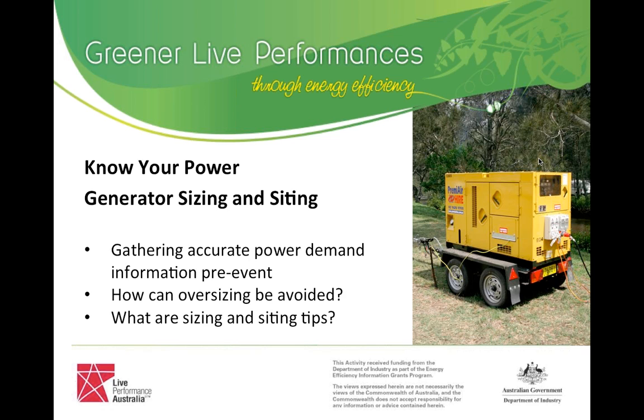Yeah. I think the events that are, you know, 21 years old, there's not much value we can add because they probably have a very good handle on it. Yeah, it's the younger, newer events that we really come into our own with sizing the generator, making sure we have the right distribution equipment, in terms of outlets on them, because they wouldn't have been that far down the road in terms of putting permanent distribution in.